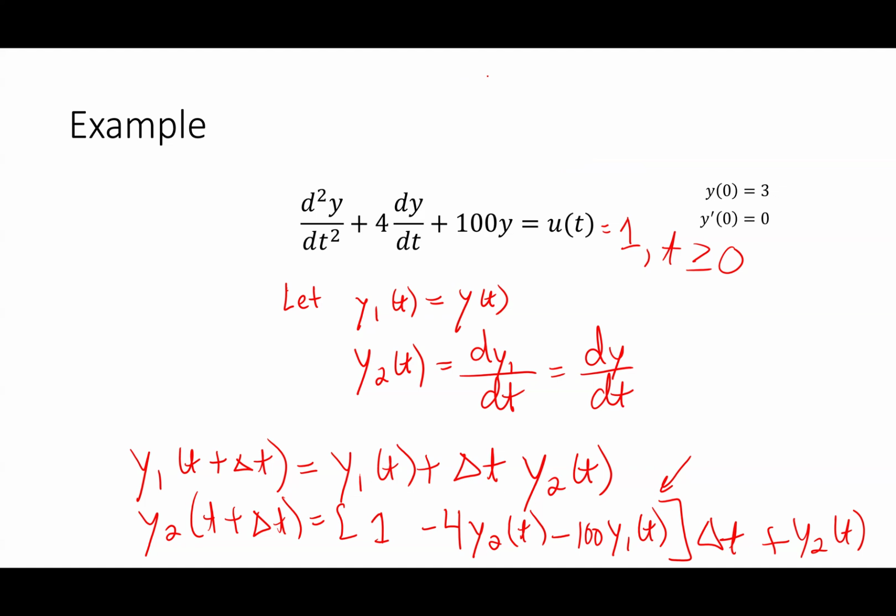What's the transient response going to be? What is the transient response always? Always, always: exponentials. And if I have second order, how many exponentials? 2. The problem is those exponentials can have complex coefficients. So in general, the transient response would be C1 e to the S1t plus C2 e to the S2t. And I've already said there are 4 options it can take, depending on the values of S1 and S2.